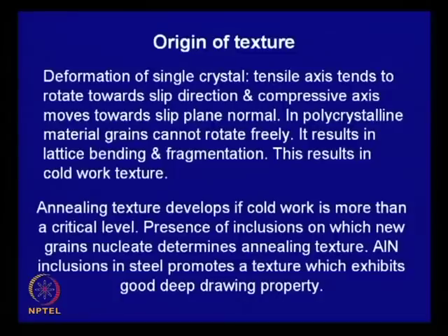Now, deformation. As we have seen earlier, if I try to recollect, the tensile axis tends to rotate towards the slip direction, then compressive axis also moves. So, that means the slip plane normal tends to move to the compressive axis.